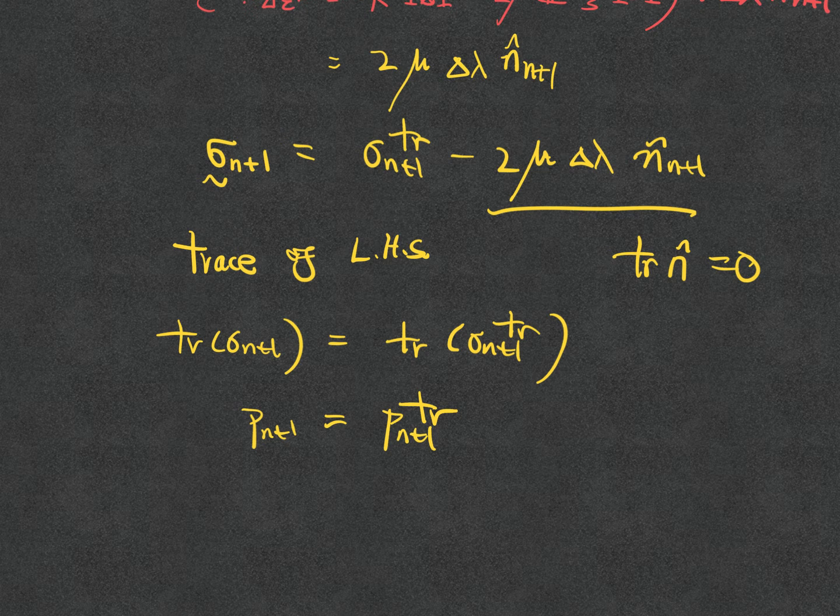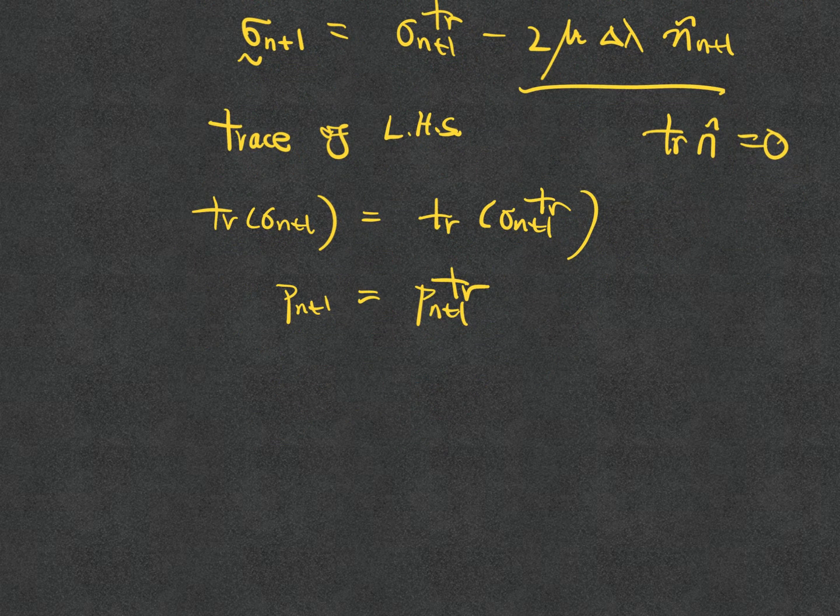Okay, so I also have an easier problem. I forget about what happened in the volumetric part. I only care about the deviatoric part. I only need to measure how much deviatoric plastic deformation I have, in particular because I don't have any volumetric plastic deformations. Does that make sense? So this is just coming from the physics. Now, how about the deviatoric?